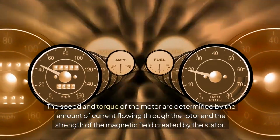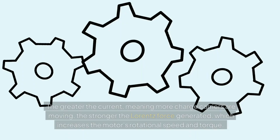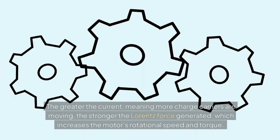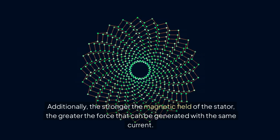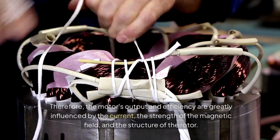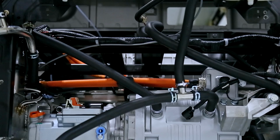4. Current and rotational speed. The speed and torque of the motor are determined by the amount of current flowing through the rotor and the strength of the magnetic field created by the stator. The greater the current, meaning more charge carriers are moving, the stronger the Lorentz force generated, which increases the motor's rotational speed and torque. Additionally, the stronger the magnetic field of the stator, the greater the force that can be generated with the same current. Therefore, the motor's output and efficiency are greatly influenced by the current, the strength of the magnetic field, and the structure of the rotor.